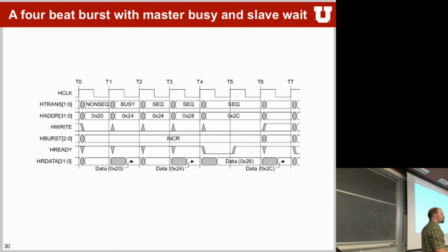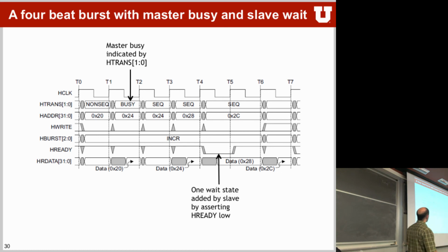It's basically the start of a burst, in this case. And then it tells it, we are busy on the transfer. So basically the increment didn't happen, and then the increment happens in the next one. And sequence means it's in a sequence of addresses, in this particular case. And then it points to what the type of the burst is and how the sequence is set up.